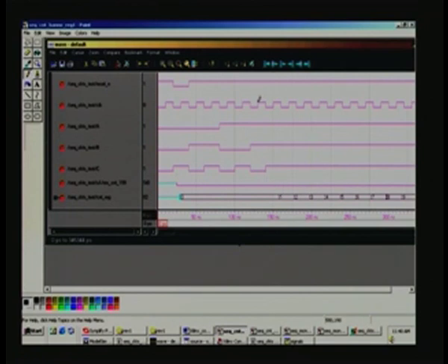Now, if you see here, this is the positive edge of the clock, and the actual counter advances not at that point, but only after a delay. For example, this may be around 2 nanoseconds or so. Every count is always delayed by the same amount. Once again you can see here, it is counting from 0, 1, 2, 3 and so on, right up to 9. We will see one more view of this towards the end of this count.